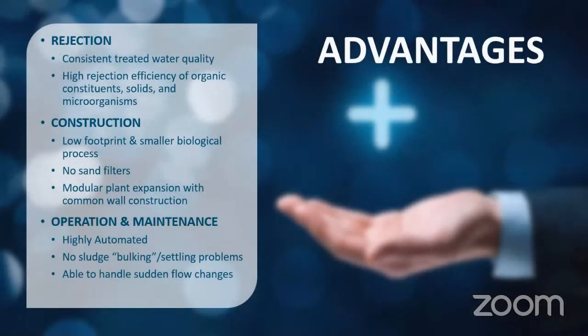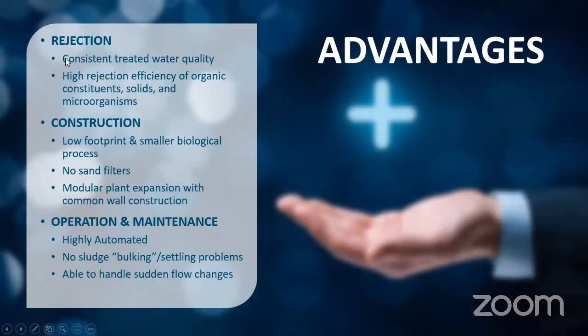What are the advantages of MBR technology? Of course, you get the basic advantage of using membrane technology: consistent treated filtrate quality, and high rejection of organics and solids, because this is something you need to ensure is not getting back into the natural water source. On the construction front, you have a very low footprint, so your cost of construction is going to be cheaper. There are no sand filters. It's a very modular plant.